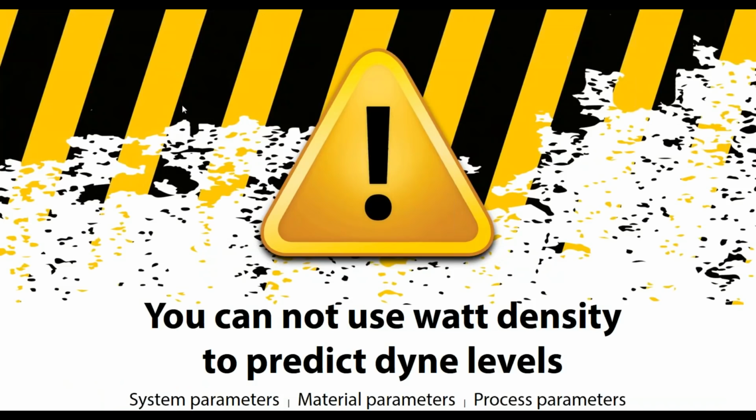Finally, in this part of the presentation, one cautionary note. You cannot use watt density to predict the Dyne number. You're probably thinking, well, I wonder why that is. Why don't these things just march linearly with each other? So if on one polypropylene film I might get a watt density of 2 and get 40 Dynes, and I run another polypropylene film at the same watt density, I don't get 40 Dynes, I get something else. And why is that? We must have to blame the corona treater for that. Well, maybe and maybe not, but we'll get into this as we go forward. But please remember, you can't use watt density to try to predict Dyne numbers.